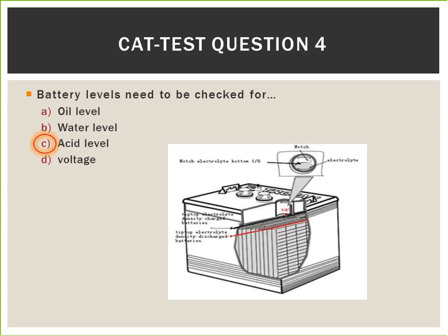The lead-acid battery is made up of plates, lead, and lead oxide with a 35% sulfuric acid and 65% water solution. This solution is called electrolyte, which causes a chemical reaction that produces electrons. When you test a battery with a hydrometer, you are measuring the amount of sulfuric acid in the electrolyte. If your reading is low, that means that the chemistry that makes electrons is lacking.